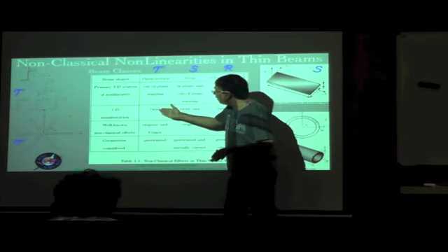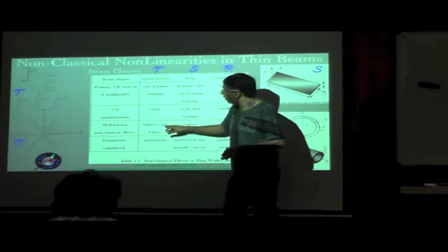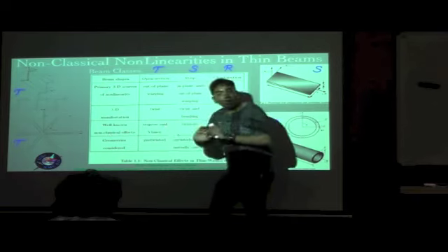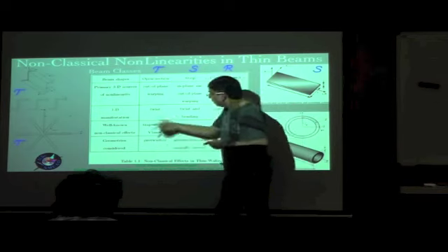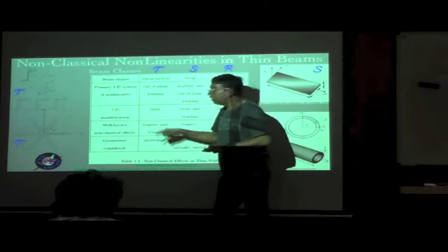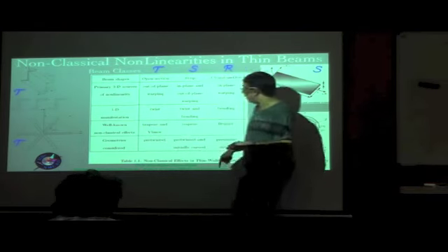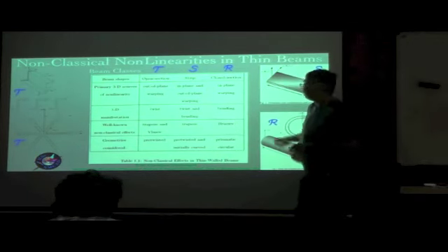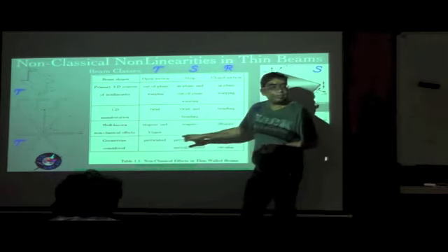Next, in terms of the nonlinear effects themselves, the well-known non-classical effects are the trapeze and Vlasov effects. I'm not only talking about nonlinear effects, but non-classical effects, which are not accounted for in that 4x4 matrix. So in that sense, not only the nonlinear trapeze effect, but also the linear but complex Vlasov effect because of the restrained warping. On the other hand, in the closed cross section, the well-known non-classical effect is Brazier. And in the case of the strip, you have trapeze as well as Brazier-like effects.